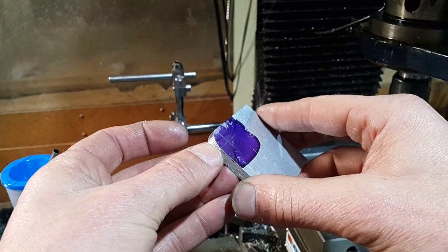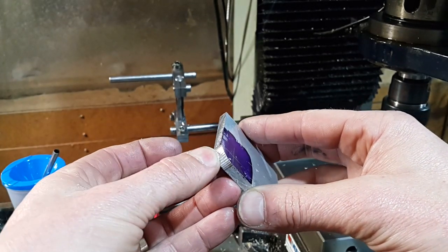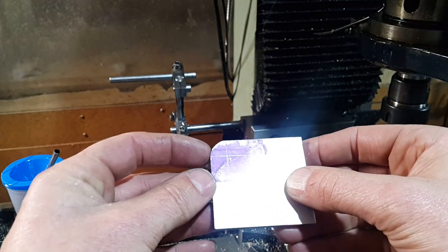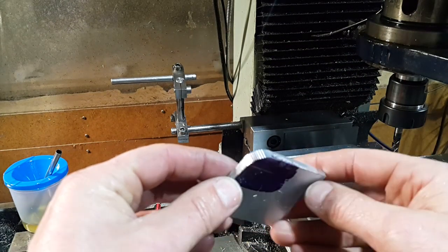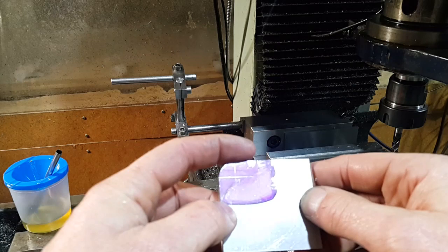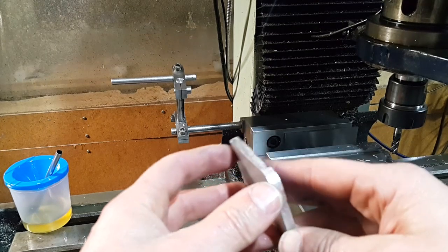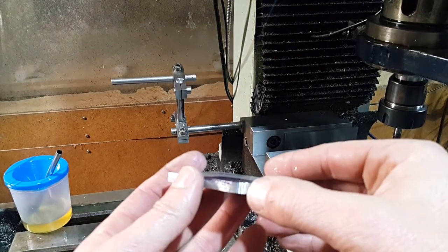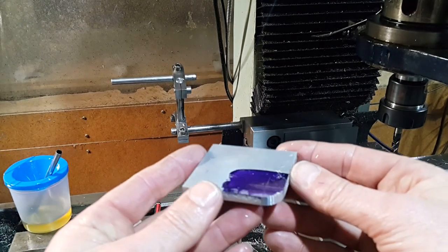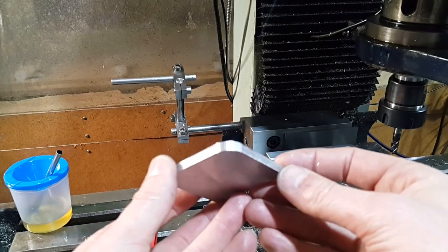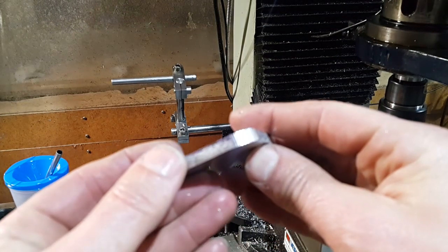If we wanted to go into the smooth setting on the DRO, we could smooth that out and do a lot more cuts. In that particular cut, we had about 18 divisions, 18 separate cuts. So if we were to use the smooth setting and double it, we'd have 36 or 38 cuts, depending on how the machine determines that. The DRO itself in the smooth setting is down to a 0.3 step over. Where we've used a 1mm step over, those lines there will be roughly about 1mm apart.